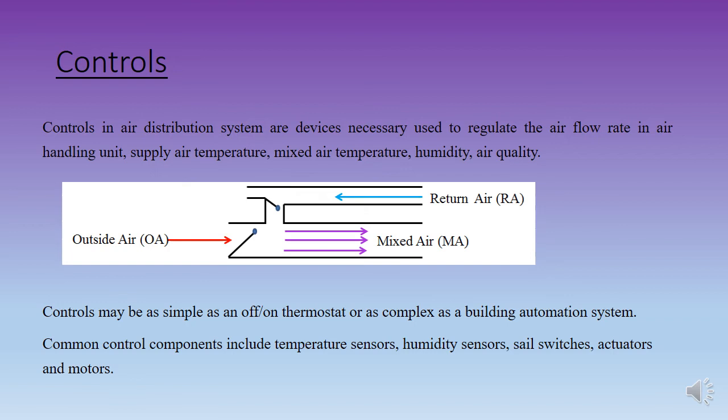And just bear in mind, if you have to choose between two sizes, you should know that when you oversize, then the friction loss will decrease, and if you undersize, the friction loss will increase.